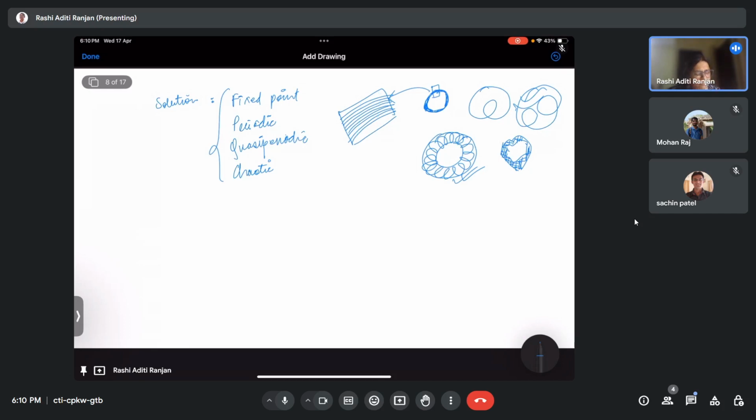However, this is also subject to error. This is not a completely correct way of saying that it is a periodic response, but it may happen that due to some error when you perform the simulation. Okay. And for the chaotic, I've already told you how you can find out whether your response is chaotic or not. Take the initial condition, simulate it, apply hold on the figure, and then change the initial condition. For example, if you have the initial condition x naught, change it to x naught plus 10 to the power minus 4.